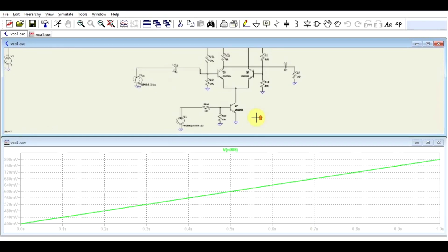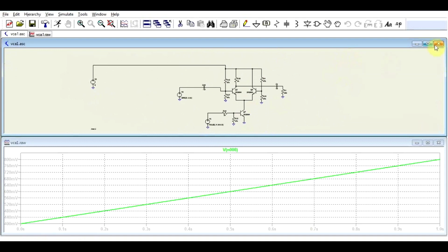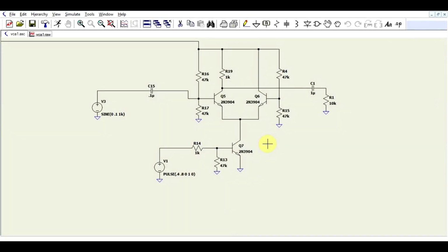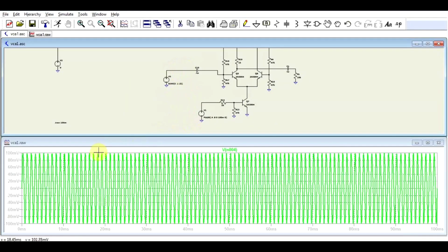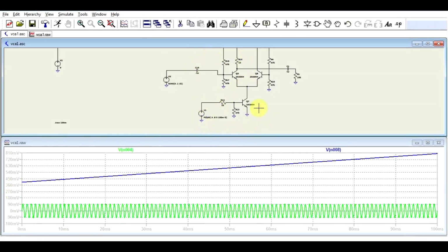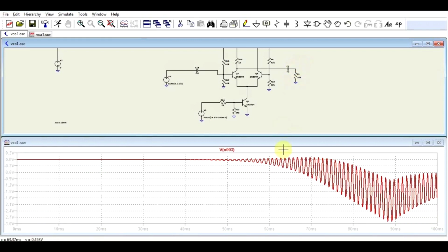Now, there are simpler ways of doing this. In its most basic form, it will contain a single transistor, but from what I could figure out, that circuit will end up distorting the signal. This is a more complicated version of this circuit, in which I have a comparator and a transistor that regulates the current going through the comparator. So by using this circuit, I take my original audio sound, I take the voltage ramp, and by combining these two, I get this sort of response. My output's amplitude will vary based on the voltage injected into this lower part of the circuit.